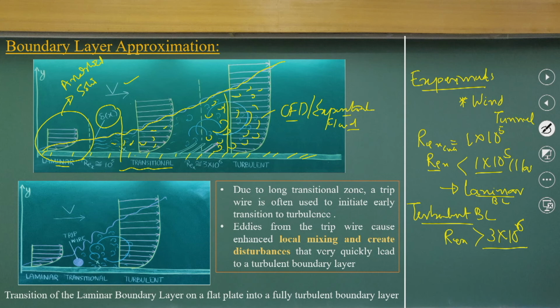No doubt the laminar flow is easy to understand, but the transitional is more complex as the generation, growth, decay of all the patterns happens here. So, the transitional part is very difficult, even though today we have very advanced CFD solvers. Still we cannot solve this transitional case, and in many design cases we try to avoid this transitional zone.